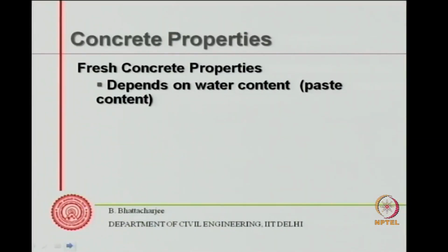This is best done by vibration in normal concrete. Of course, there is special concrete called self-compacting concrete, which is becoming more and more popular nowadays. But in normal concrete, we adopt vibration in order to drive out the air and get the desired shape according to the mold. Therefore, concrete must be able to flow. It must be able to flow. Now, this flowability, if we look at it, aggregates are not flowable.